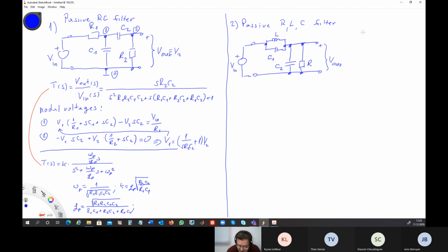So this was the example. If you look at these two guys, this one is Z2, and this one here was equal to Z1. Then you can solve this more simply. V out over V in has the form Z2 over Z1 plus Z2. This is what one of you thought for the first example. Okay, and then when we calculate it, we have the following form.